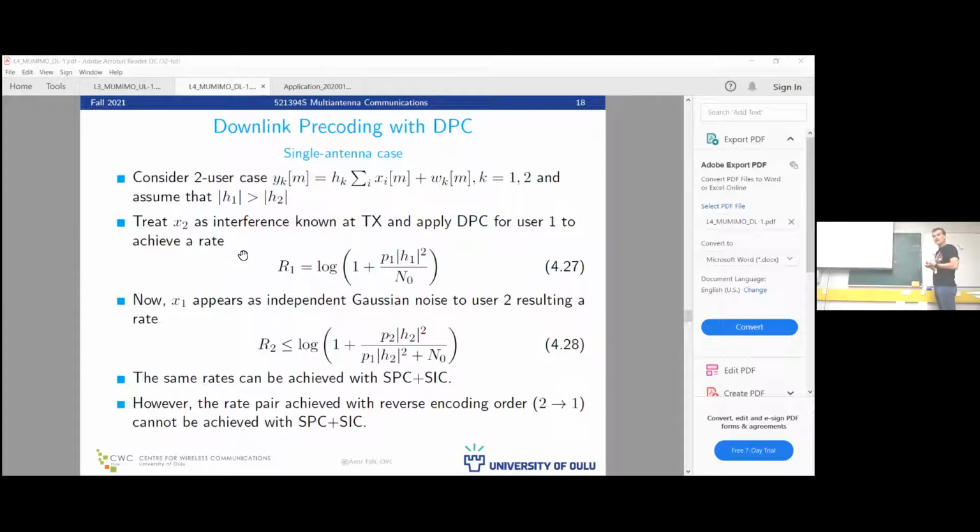But if I see, I mean, some intuition from the previous extended figures, let's say we have for QPSK, we had the 16 constellations, right? From that, we can decode without knowing the other user data also. Right? Yes, it's just a new origo. The other user data sets the new origo, and the user does not know about the origo, right? Because it just sees the summation of these two vectors, right? So it just simply chooses the point which is closest to the received noisy sample, right? Okay. The reference constellation has to be known.